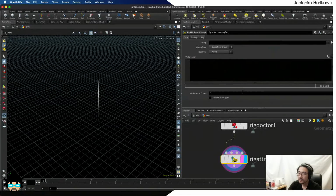Within this rig attribute wrangle, I'm going to modify the local transform of each point based on the position of the point, or maybe the parameter of the point, then bend it to some random direction, or maybe derive from a noise-related value.